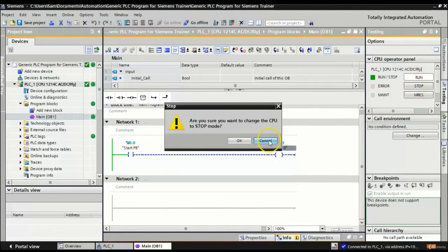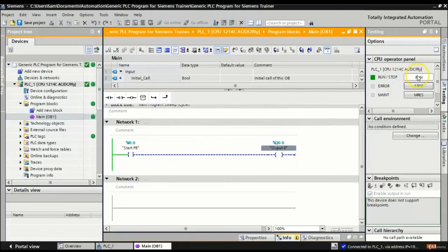And over here, you may have to stop and run the PLC. It depends, some of the PLCs will go right into run mode, others you have to hit run. So here you can see that I'm pressing the push button and that's green all the way through to my output. You should see that your output 0 LED has turned on. And also, when the input 0 is pressed, you're seeing the LED corresponding to that input 0 turn on as well.